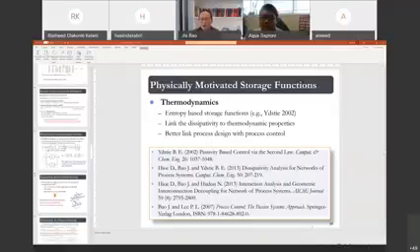So if we assume the process is passive, or a special case of dissipativeness, then you can have a PID controller where all the coefficients are adaptive, but you don't have a problem of stability because the stability is ensured by the dissipativity condition. So that's one of the ways you can think.